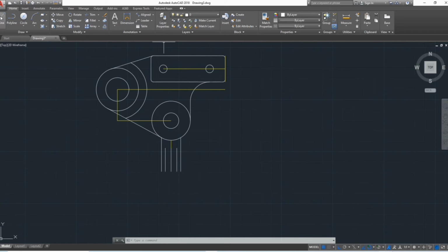Next, draw another line starting from here with a measurement of 0.5, then enter. Another one going to the right measuring 0.76, then enter. Another line downward measuring 1.06, enter, and then just connect it to the circumference of the circle. Then after that, trim the excess line.